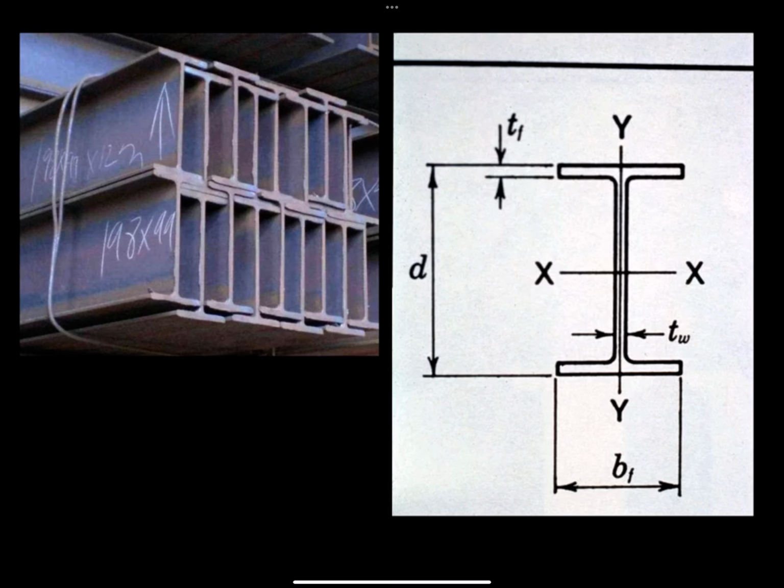So why is weight important for a steel section? Two reasons. One is the weight affects the structural performance of the steel section. So obviously heavier sections are stronger structurally. And the second reason is cost. So steel is costed by its weight. We don't buy wood by weight. We don't buy bricks and blocks by weight, but steel is costed by its weight.